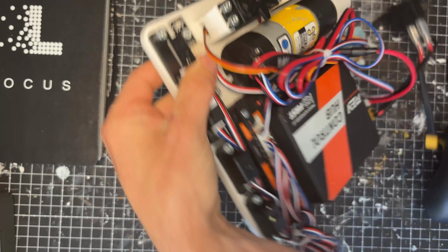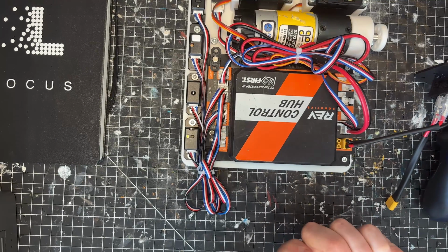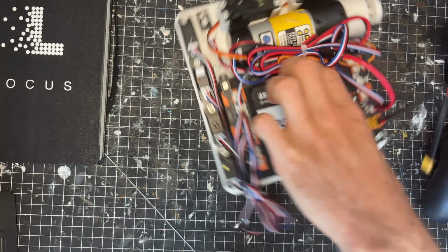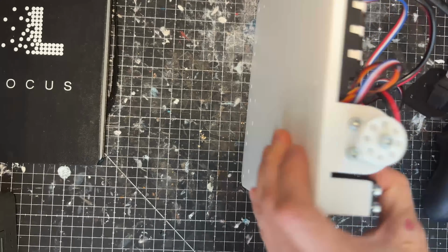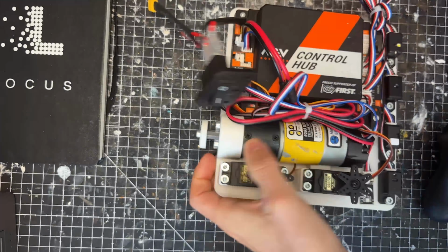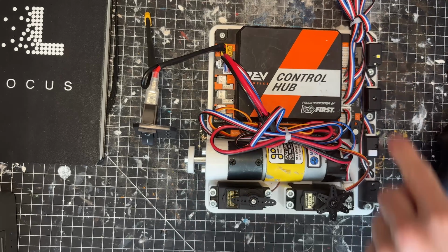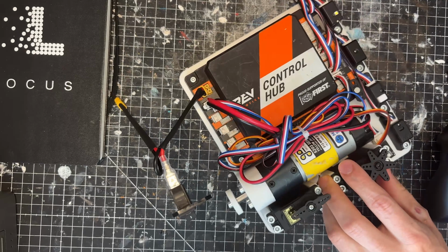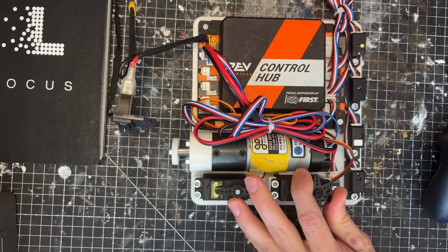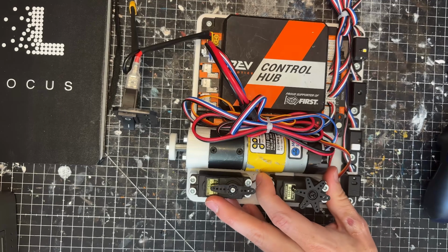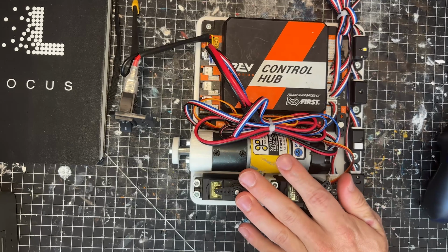If I had it placed on my robot like this, it would still be logo up, but my USB would be facing in reverse or backwards. You are allowed to have this thing facing to the side. You could have it facing upside down. The one thing I'd recommend is that you set this up square on your robot. You don't want to be setting this thing up on a weird angle because that's just going to make life a lot harder. You can do it, but it's just going to add some extra programming when you realistically could set this thing up in a square orientation and you don't have to do any extra calculations to account for that.